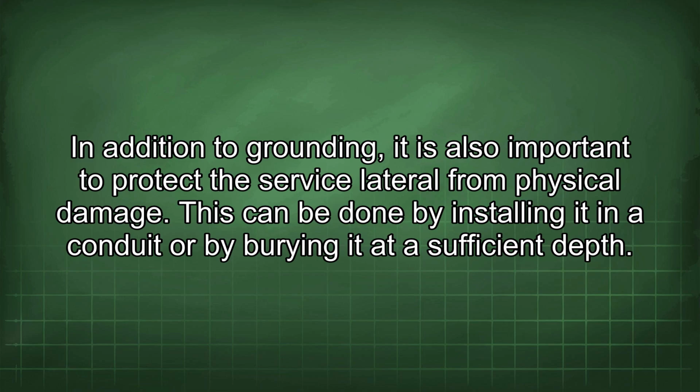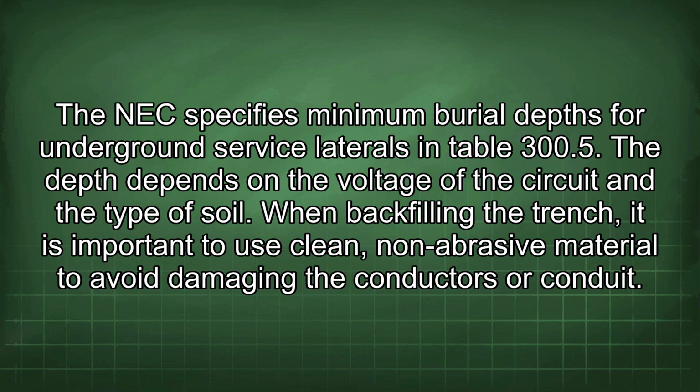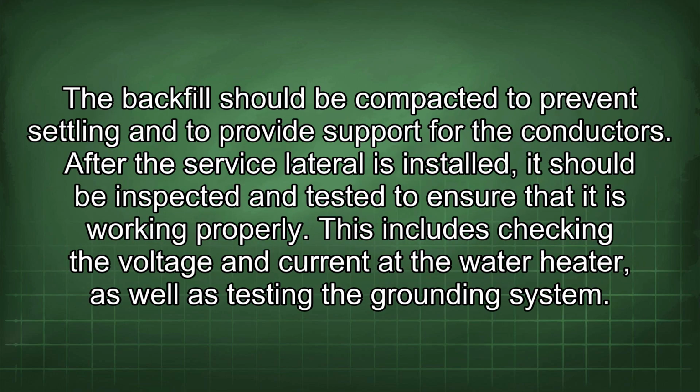In addition to grounding, it is also important to protect the service lateral from physical damage. This can be done by installing it in a conduit or by burying it at a sufficient depth. The NEC specifies minimum burial depths for underground service laterals in Table 300.5. The depth depends on the voltage of the circuit and the type of soil. When backfilling the trench, it is important to use clean, non-abrasive material to avoid damaging the conductors or conduit. The backfill should be compacted to prevent settling and to provide support for the conductors.